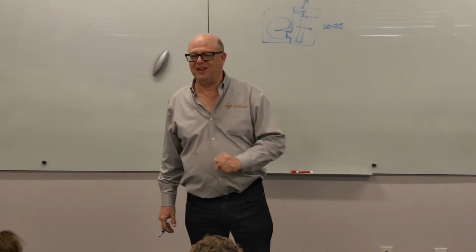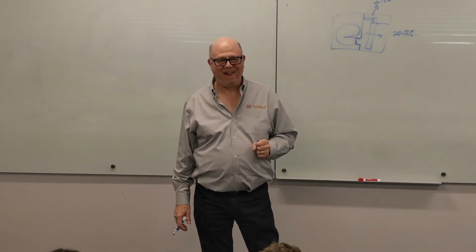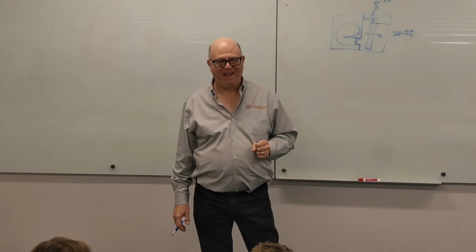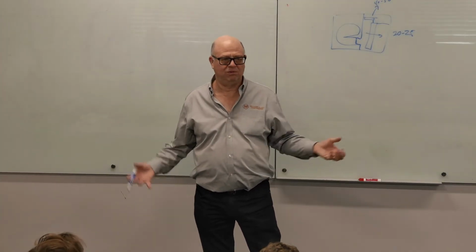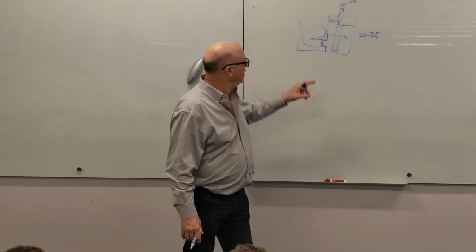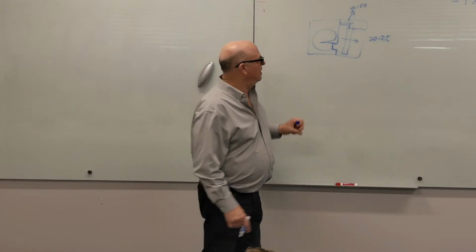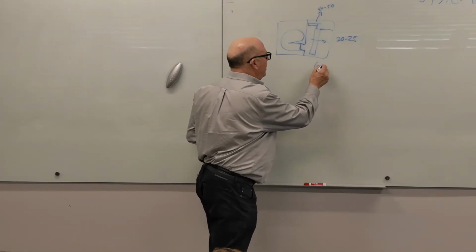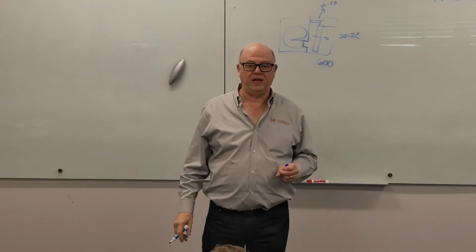What's the other reason the heating coil can be so much smaller? It's the face velocity. You say, well, what's that have to do with anything? Well, that coil's wet. Rule of thumb is you never, ever want to exceed 600 feet per minute on a cooling coil, and that's sketchy.